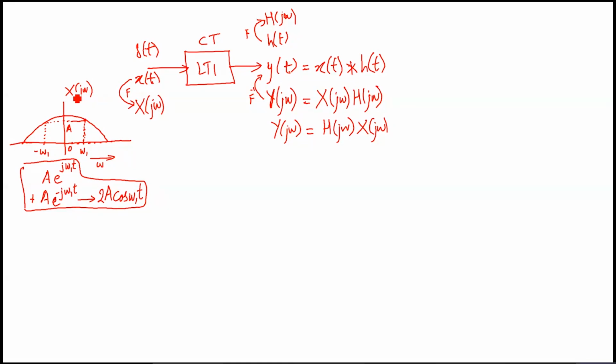Similarly, Y(jω) is supposed to be the angular frequency content, or frequency content, of your output y(t). Now once this frequency content goes inside a system, the output that you get is Y(jω), or the frequency content of the output. So what actually happens? See this equation right here. The input frequency content gets multiplied by H(jω).